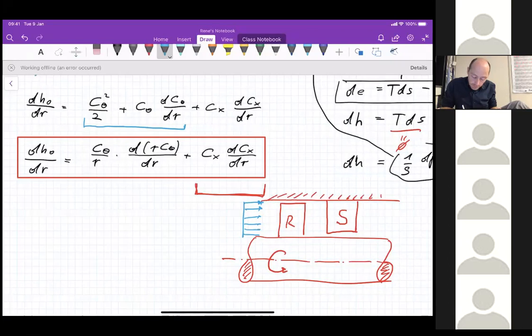So if this is the profile of the axial velocity as a constant, I know that this term is going to be 0. And most of the time also I can already say that in my design I would also like to have a constant total enthalpy across the radius. Then I can say that this term has to be 0. Let's say this is one design that I can choose. Of course, I don't need to choose constant enthalpy across the radius, and it's in fact not always done. And you can optimize it for efficiency. Maybe if you optimize for efficiency, you will see that actually the enthalpy will have to change.